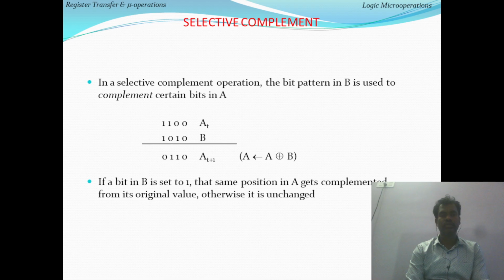Next are shift micro operations. These are serial shift operations. At a time it performs one shift in one clock cycle. If you want to perform more than one shift, we can indicate the count, the number of times it will be repeated.